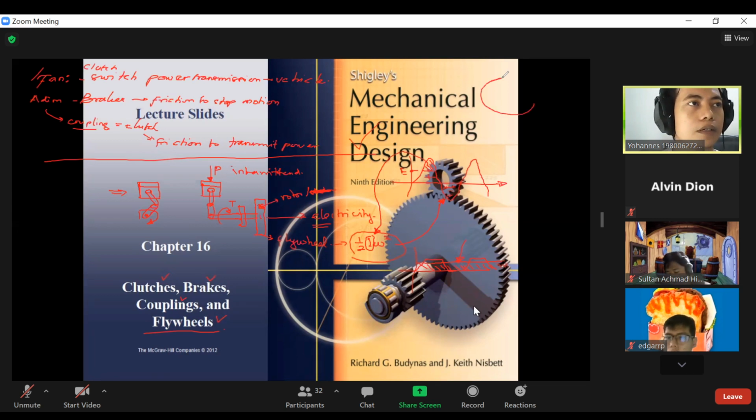And then the shape of the flywheel usually has the ring where the mass is concentrated. So this is mass. But here it's just a thin plate, or you can expect like a rim here where the mass is neglected. So this is the main mass, and this mass is neglected because it is small. So you focus on how you design this geometry in order to obtain appropriate inertia for the flywheel to absorb the required energy.